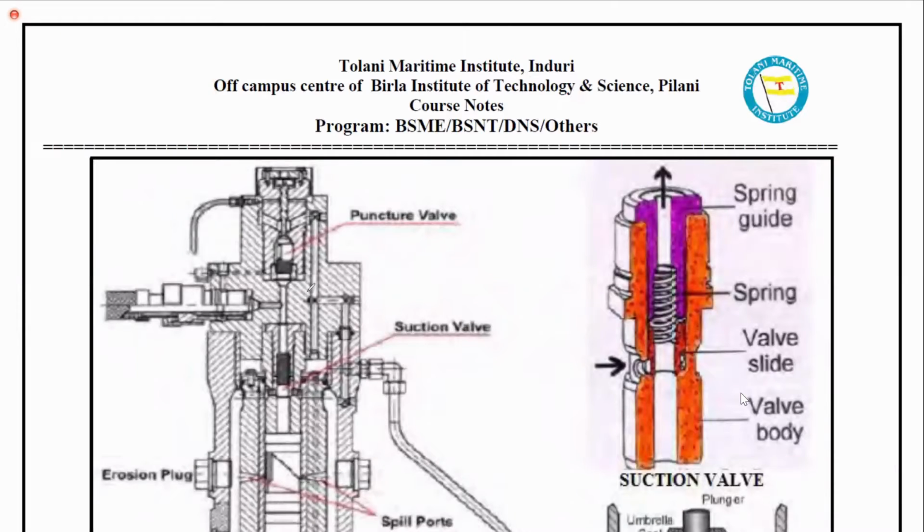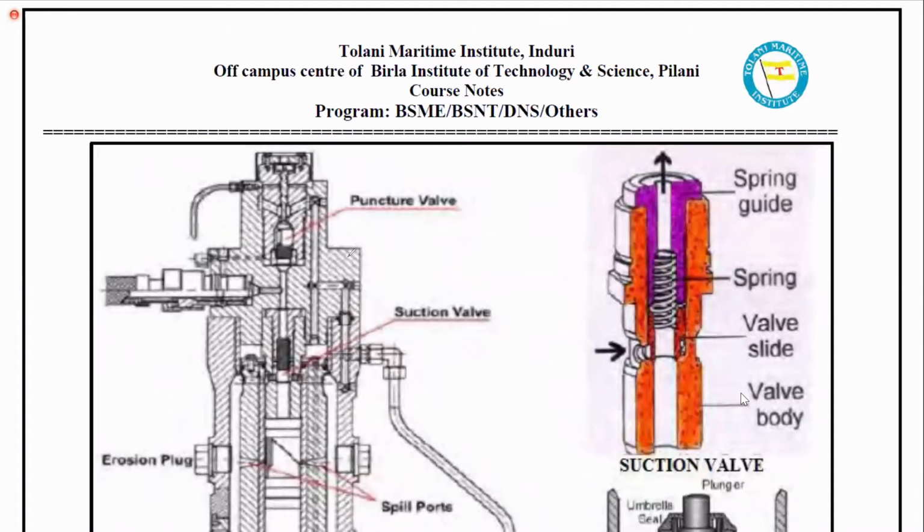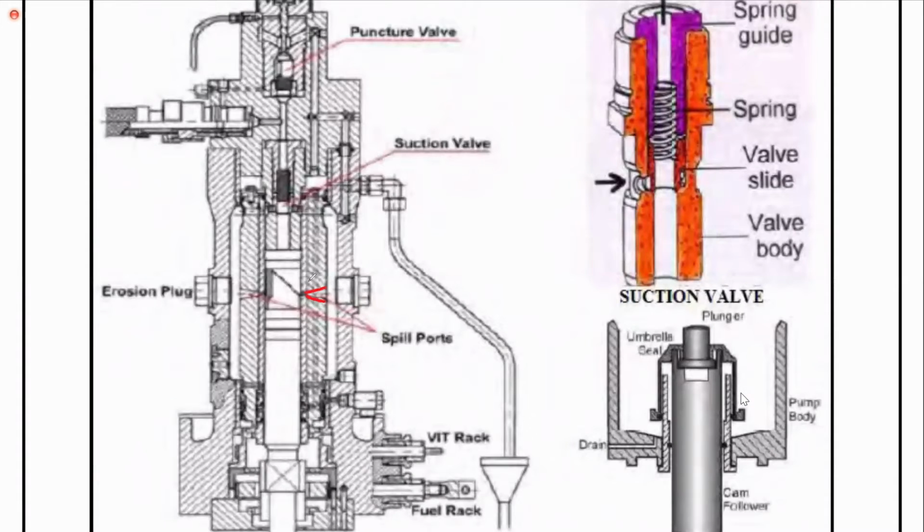The relative position of the barrel's spill port and suction port changes. This spill port is either going to move up or this spill port is going to move down. So if the barrel moves up, what will happen to the fuel injection timing? Sir, it will retard. Delay, sir. Yes, retard is delay. Yes, exactly. So it will retard.